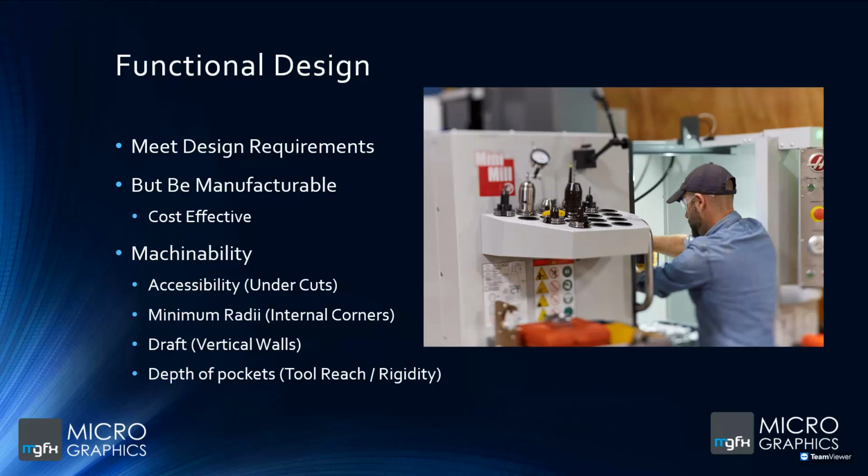Looking specifically at where there may be areas where there's undercuts that could require a second or a third operation or setup within the machine to be able to access those areas. We'll look at minimum radii inspections to be able to see where fillets match a certain minimum radius, or if they fall outside of a minimum and maximum range, let's say, of tools that you have available.